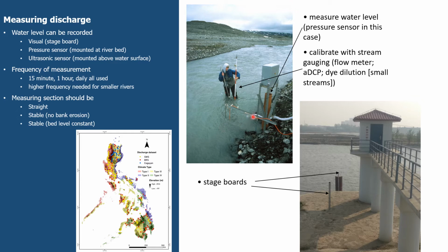We had to make measurements where we could, and here the banks were subject to erosion, as you can see. The river bed was also somewhat variable. We had to keep resurveying the geometry over a few weeks because the riverbed kept changing, which is not ideal.